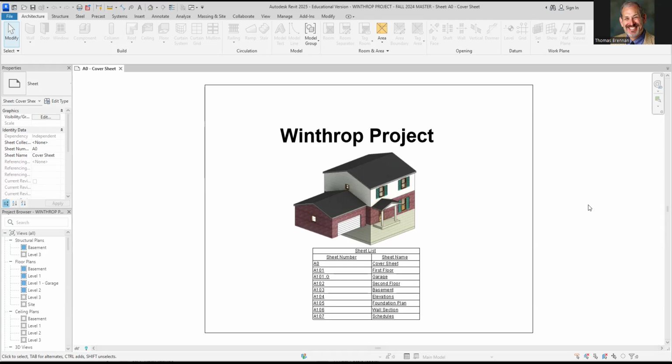A permanent wood foundation is essentially where instead of having poured walls in your basement, you actually have what we used to call Wolmanized or pressure treated lumber, okay? And I think that the actual percentage when you do a permanent wood foundation, it's something like twice or 3 times what it is for a deck. So it's actually really built to stand. And the house I built is still standing there since it was built in 1992. So, what are you going on now? Going on close to 30 some years.